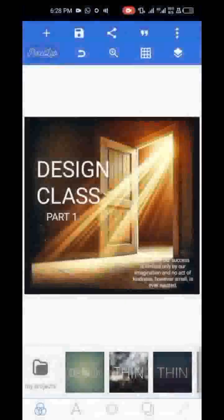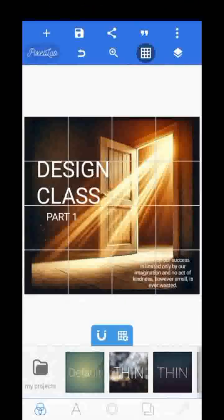So the next icon we have there is the grid option. The grid helps you to properly align your text, your items, your design elements. It helps you to do proper alignment so that your design will not be out of alignment. So if you activate the grid, it will help you to properly align your text, your shapes and your elements in your design. So your design will be very neat and professional. When you're done with the grid, you can click on it to deactivate it.